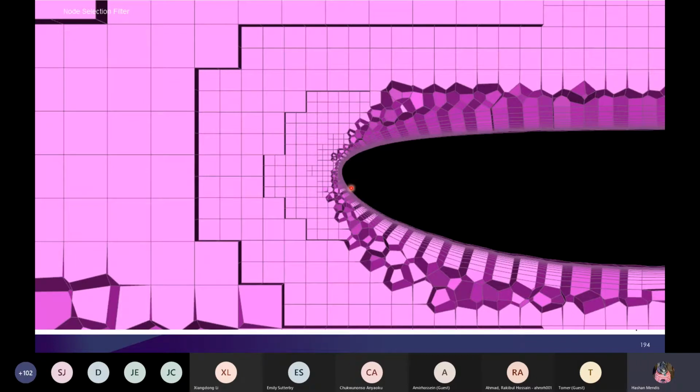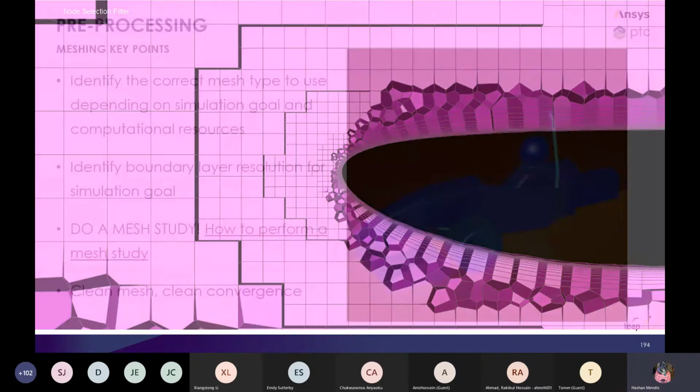And maybe you do a mesh study, right? So maybe you initially have 8 elements capturing that curvature, and then you run another simulation where you've got 16 elements capturing that curvature. You compare the results, or maybe you compare the CP on the actual wing, and you look at what's happening around that front wing and around that nose, and ask yourself, is there a large difference between these two? What am I interested in? Force, all right, is there a large change in downforce or drag? And you'll have to make that engineering decision. Is it appropriate? Do I need to make finer changes? How much accuracy do I actually need as well?